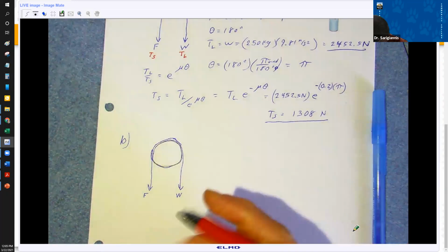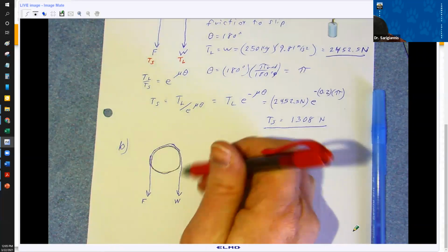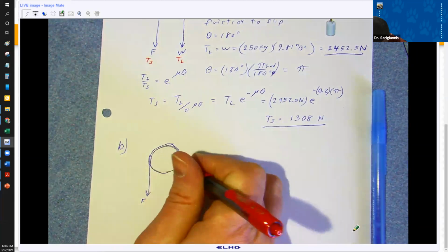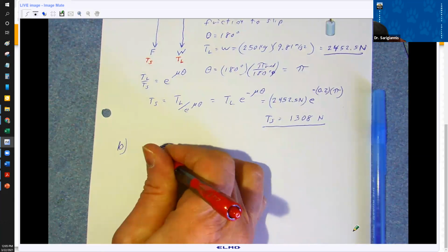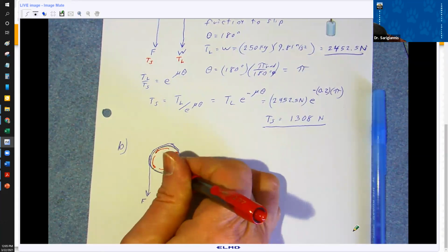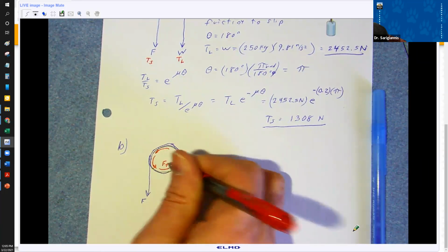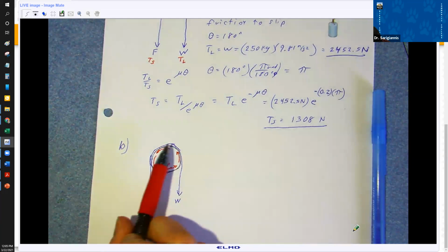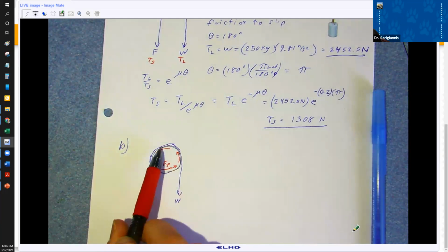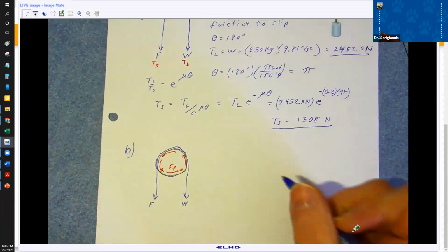And inside here again, you've got to think about which direction I'm looking to prevent slip in. I want to prevent slip from happening this way, so the friction force acts in the opposite direction. And because this time the cord goes all the way around, your force of friction acts pretty much anywhere the rope contacts the pipe, which is going to be one loop plus a half. So 540 degrees.